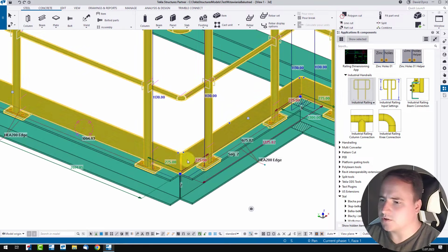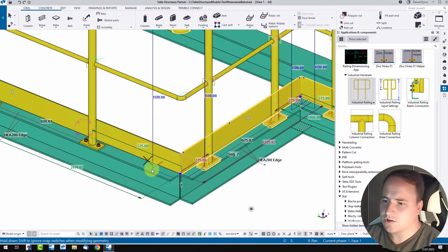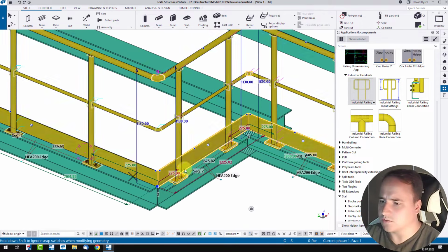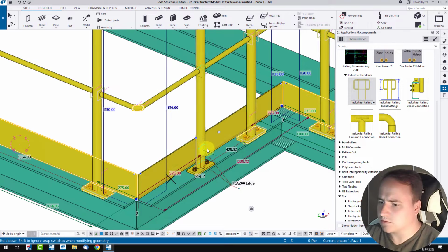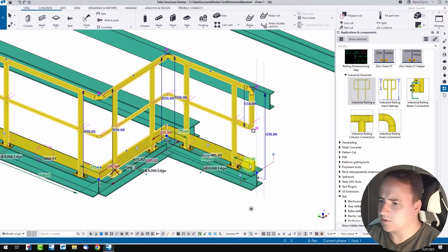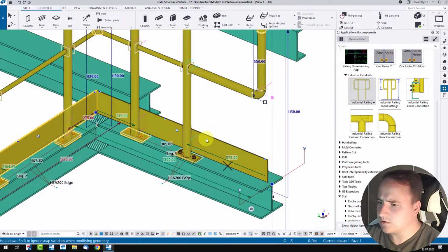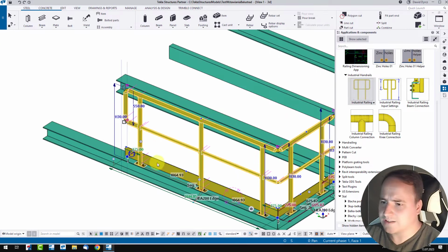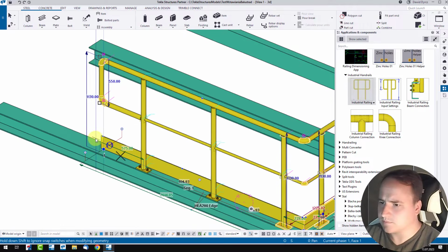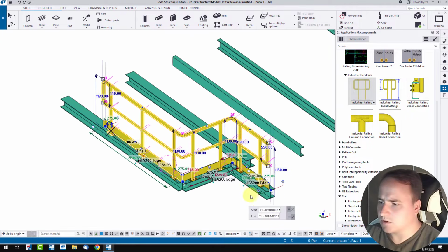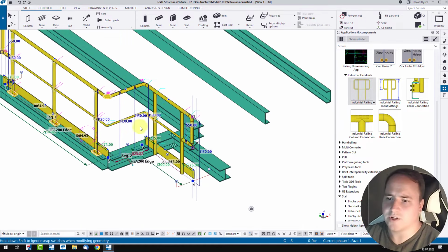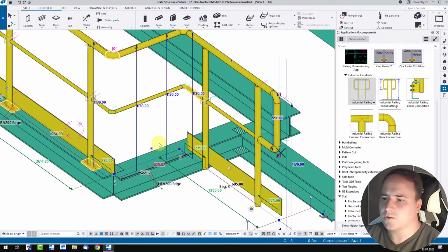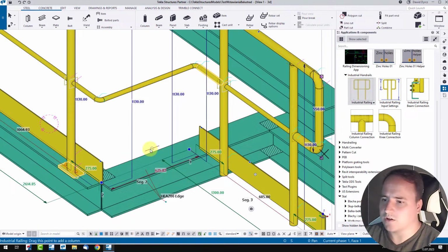On the segment corner you can see these dimensions which change the position of the first column. The same on the end and on the start. If a segment is too short, then no automatic columns are created, but you can create these columns manually.